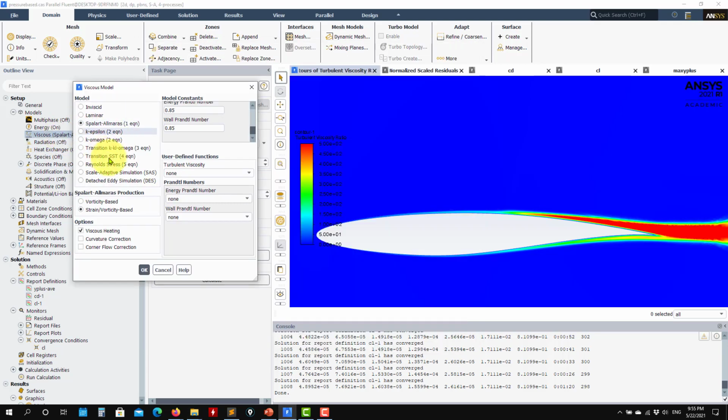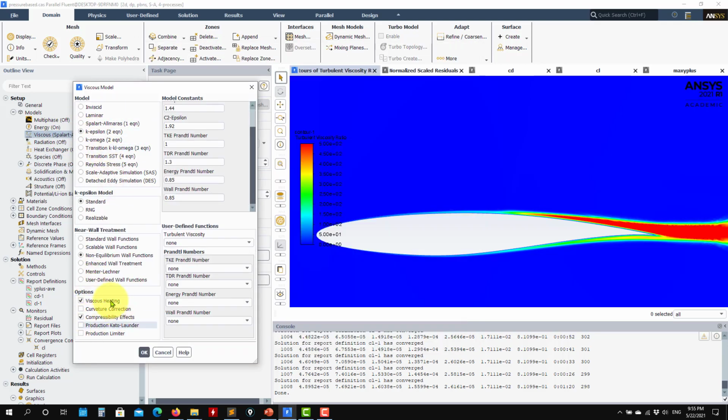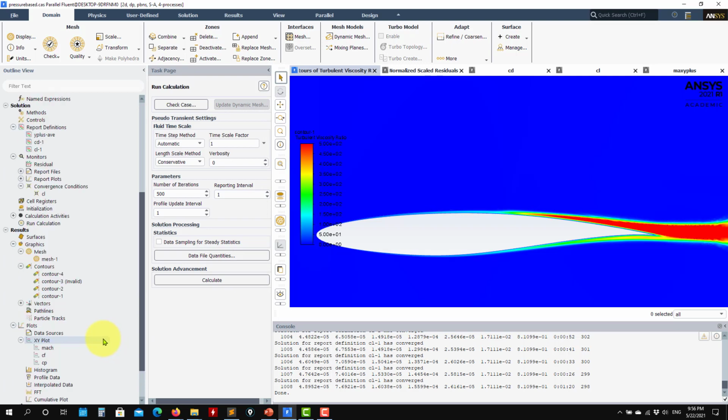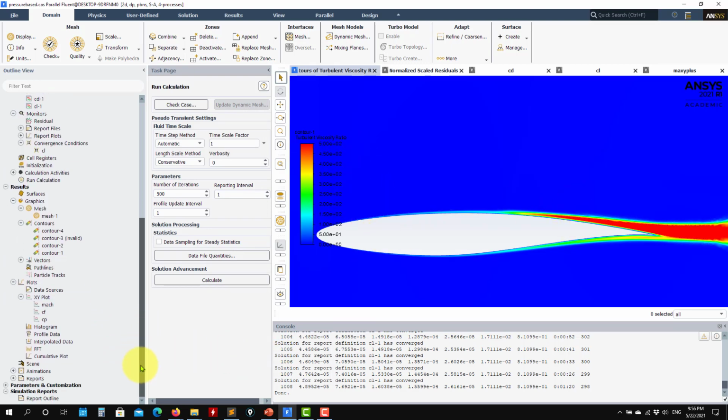Also, you can try different models, K epsilon or K omega family, enable this limiter. Okay, you can play around to reduce or increase this value. I don't recommend you to move it because 10 is a good value, it has been calibrated. Okay, and also you can try to do the plot of the normalized velocity. Okay, that shouldn't be that difficult. So that's all for this case.